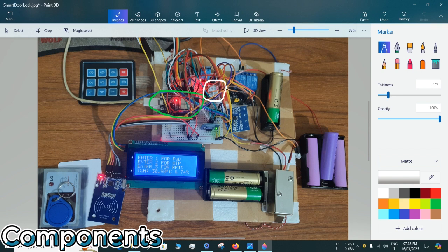You must ensure that your power source is capable of supplying enough current to drive the module to transmit messages and phone calls. Another thing is that it is very sensitive to power. That means if you are connecting the power source with a jumper cable to the VCC pin of the SIM800L GSM module, then it may not establish on the network, blinking once in every second. So in order to avoid this problem, one thing you can do is directly solder the power source with the VCC pin of the SIM800L GSM module, or directly plug in the positive terminal of the battery to the VCC pin without using any kind of jumpers.